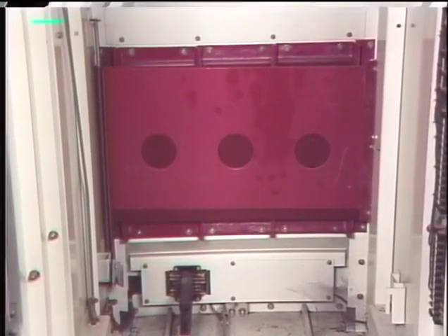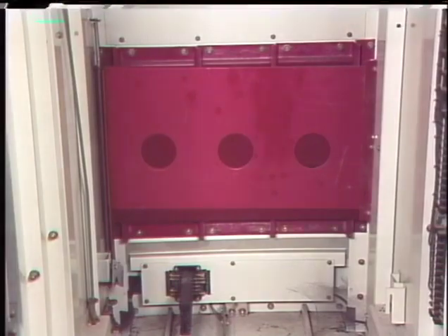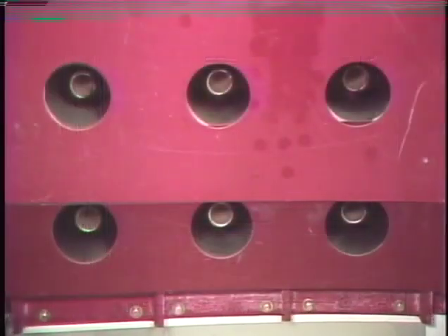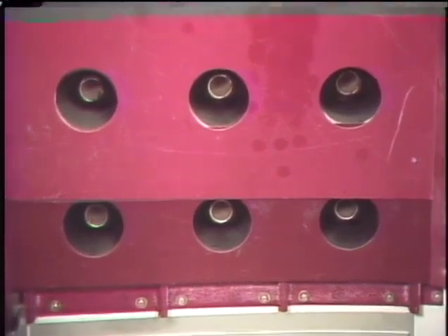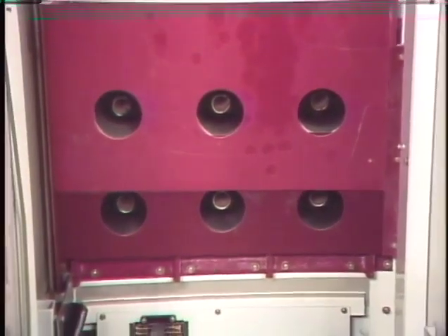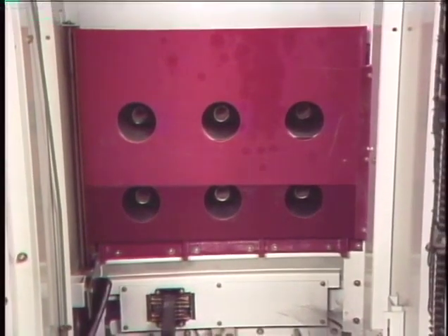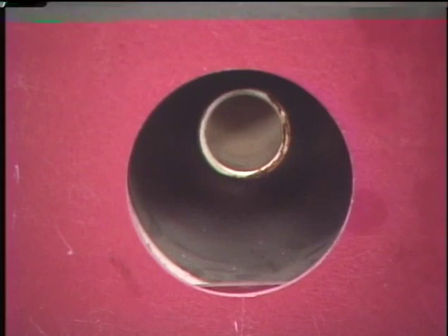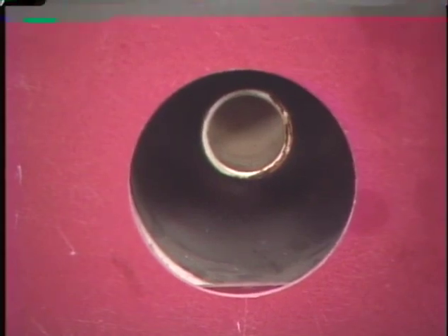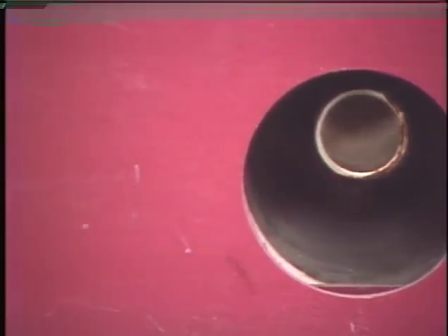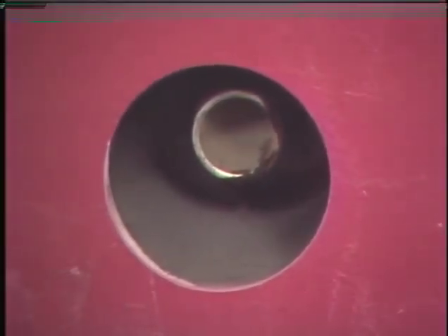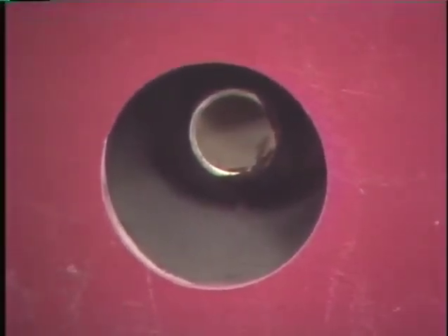Sometimes these connections are behind a protective shutter. The shutter can be opened manually so that the connections can be visually inspected. When inspecting the connections, keep a safe distance from them and follow all company safety procedures that apply. Keep all tools and hands outside the shutters and visually inspect each connection for burned, broken, or worn parts that might result in a poor breaker connection.